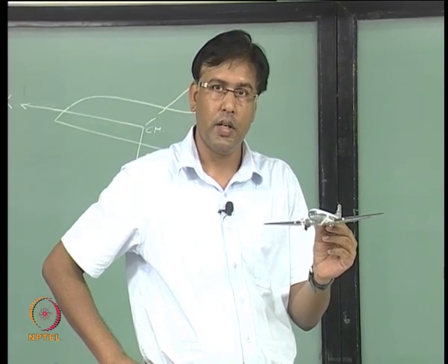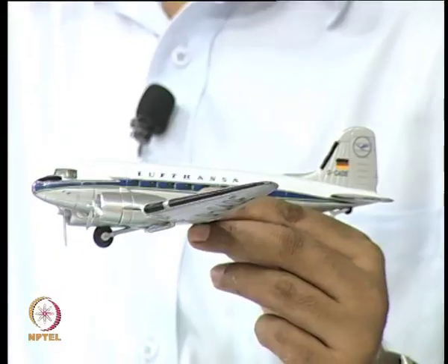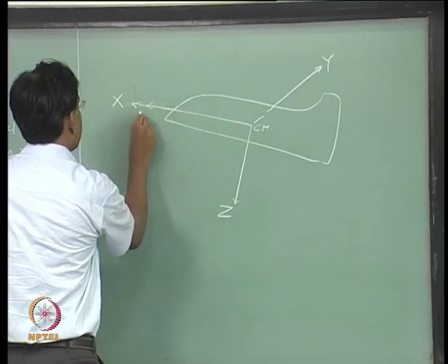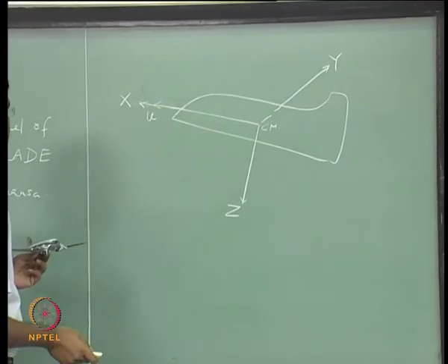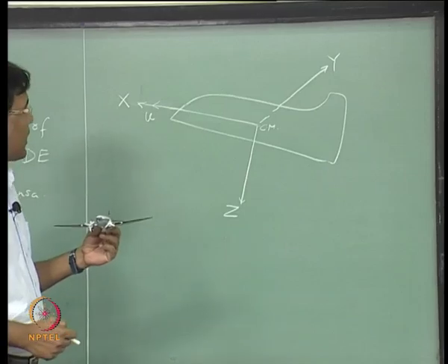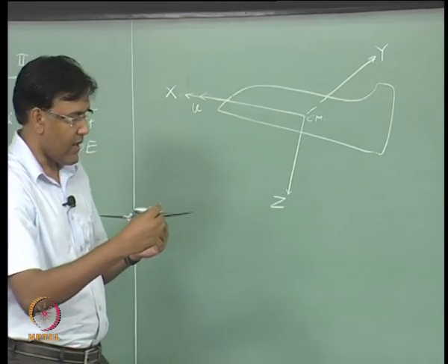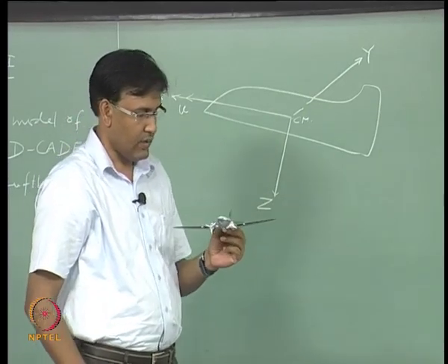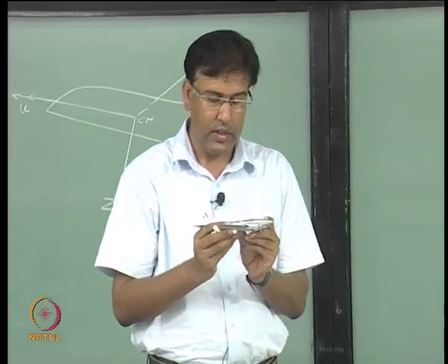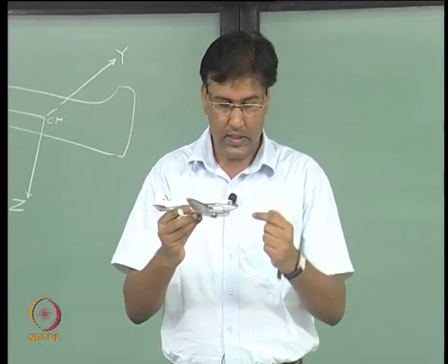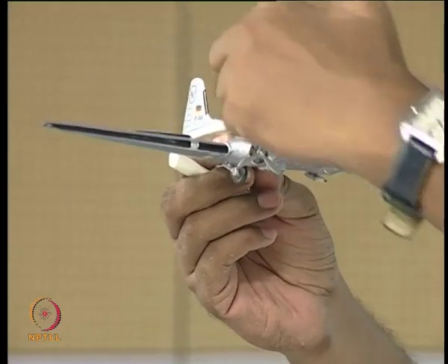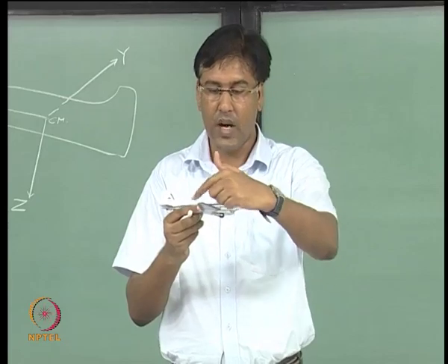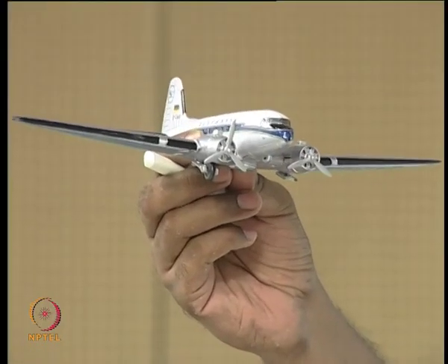was associated with the variable u, that was the velocity of aircraft along its own x axis. The side velocity is along the y axis, which is along the span of the wing, and if you look at this system, the right handed system tells us that if this is the x axis, the y axis is away from me along this part of the wing, and the z axis is downward.